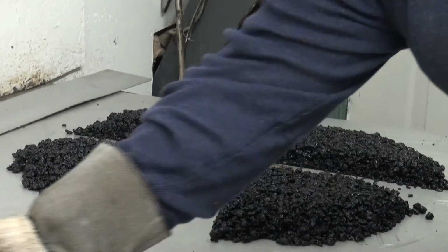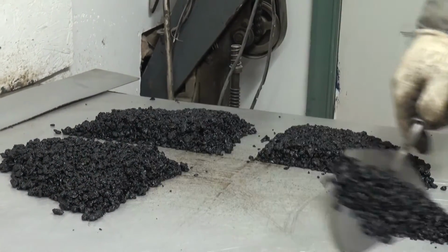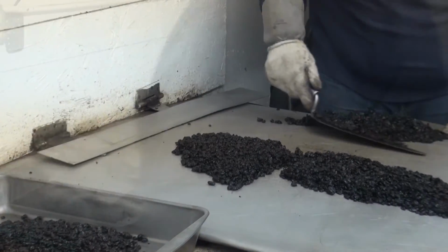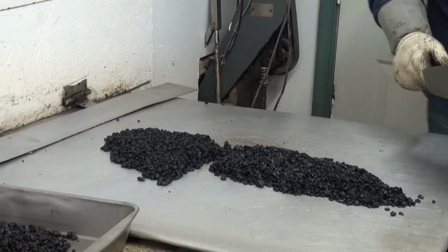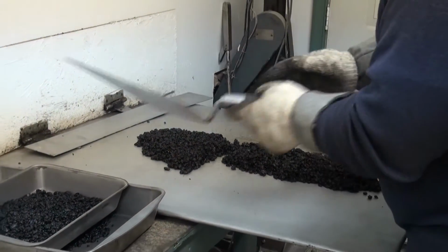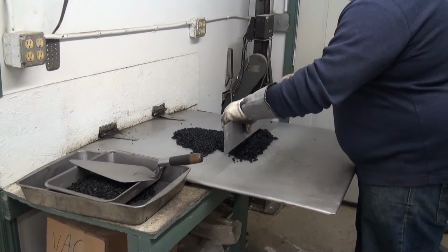From here, he'll start removing 1 quarter at a time. He's putting this first quarter in a pan, possibly for testing or for saving. Notice he moved one edge over out of the way so he can take the other quarter. Those now are together in this pan. Now, typically you'll find this happens quite a lot. The other half of material is still too big to do any testing.